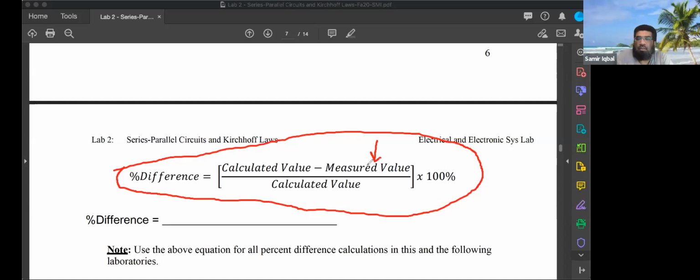So the values of resistance can be off by 5 to 10%. For one resistance, that can be off 5 to 10%. And then you have a bunch of resistances connected. What do you think is going to happen to those tolerances? They're going to become bigger, right? So each one will be contributing some offset up or down, right?